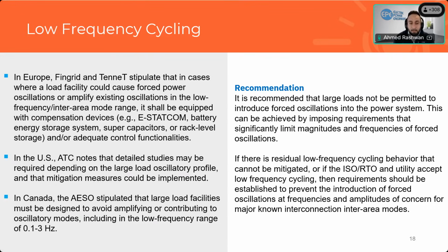And in Canada, AESO stipulated that large load facilities again need to be designed to avoid amplifying or contributing to oscillatory modes of concern in the Western Interconnection. So overall, from a recommendation perspective, I think it's important to start from a low frequency oscillation cycling perspective, that we not encourage or permit the introduction of those types of oscillations onto the system.